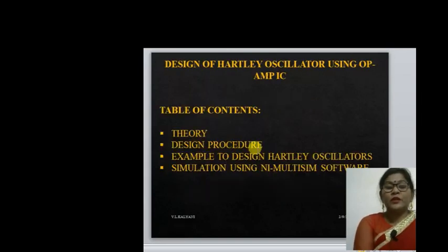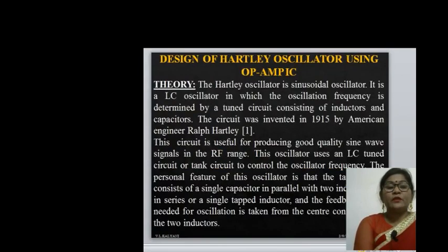We will also discuss the design procedure, then an example to design the Hartley oscillator, and the simulation using NI-Multisim software. This is the basic working of the Hartley oscillator using op-amp IC. The Hartley oscillator is a sinusoidal oscillator, so it produces a sine waveform at the output, and it is an LC oscillator in which the oscillation frequency is determined by a tuned circuit consisting of the inductor L and the capacitor C.